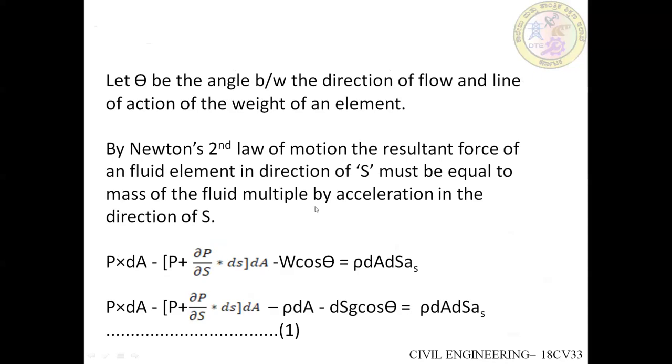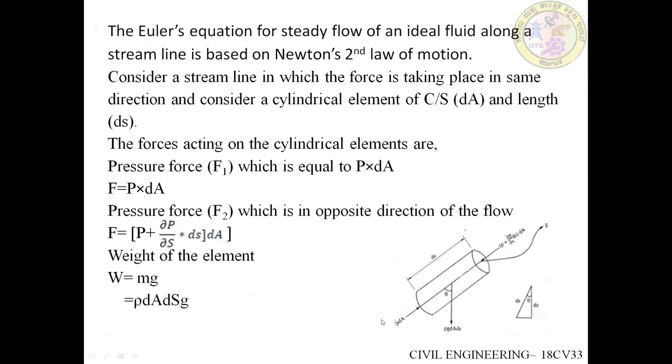By applying Newton's second law of motion, the resultant force on the fluid element in the direction of S must be equal to, again, Fx equals m into A. For Fx, we have to consider all the forces acting in the x direction. In this figure you can see one force, the second force, and the third force is the weight component, which you have to resolve.